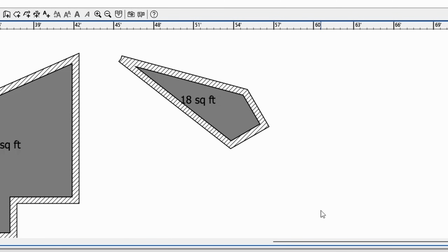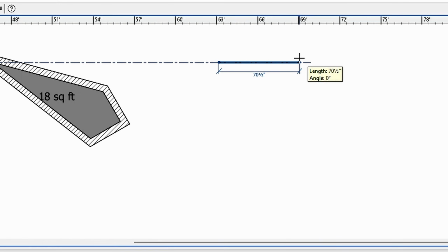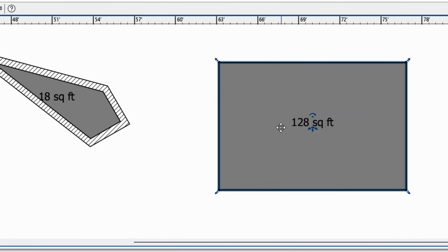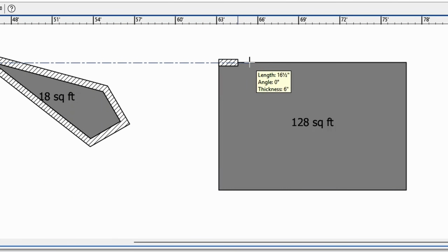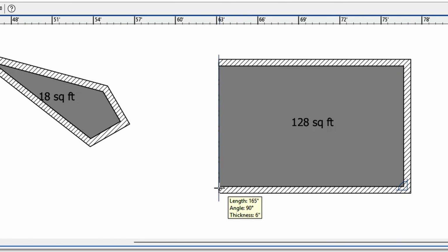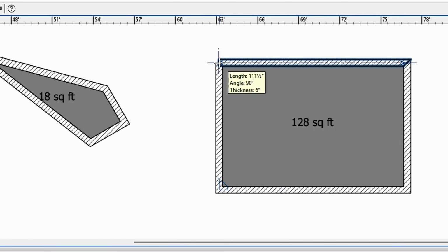If you want to start with a foundation first, then select Create Rooms tool and draw a foundation with your desired dimensions. Once it's done, select Create Walls tool in the toolbar and just double-click on the surface. Alternatively, you can also create a wall around your foundation manually. To do this, just click on its corners and draw 4 walls. Once it's done, double-click on the starting point.